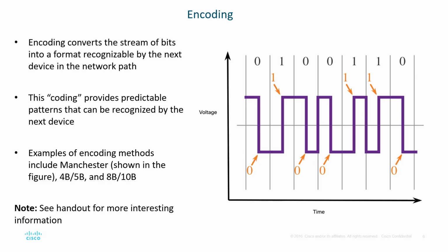In this example here, within the Manchester, what the Manchester does, so as to not overtax one wire over the other, in the middle of a bit time, it will transition its state. So if it starts out as a 0, it is going to transition to a 1. If it starts out as a 1, it's going to transition to a 0. So in this example here, we started out high as a 1, and then we went mid-bit stream, and then we went down to a 0.